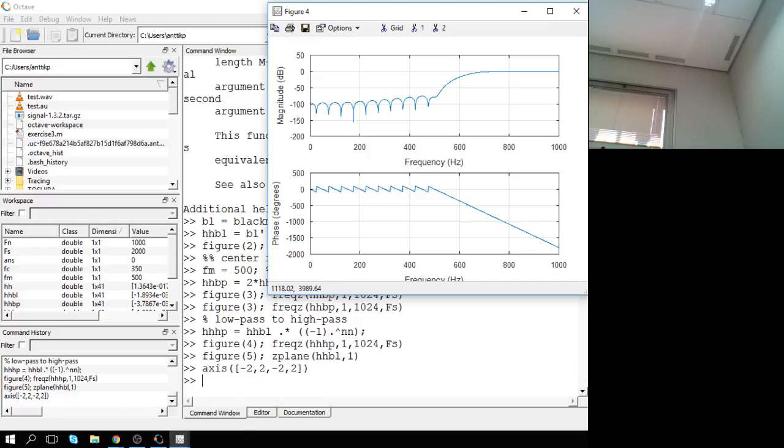Just one warning: when you are adding these filters, you are also adding their stop band properties, so you are pushing the stop band attenuation a little bit less. You can expect to read 3 dB less attenuation on the stop band, but usually that's not a big deal.